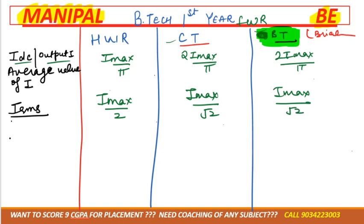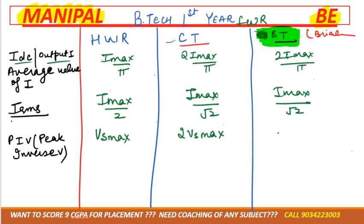Next time they can ask the peak inverse voltage. PIV stands for peak inverse voltage, the maximum voltage, and the formula for that is VS maximum. Only in the center tap case it is different, 2 VS maximum. Okay, only this one is different in center tap. Okay, why is that? Because in center tap there is a tapping at the center, and the center is connected to the transformer, with VS max in the upper half and VS max in the lower half. That's how it becomes.